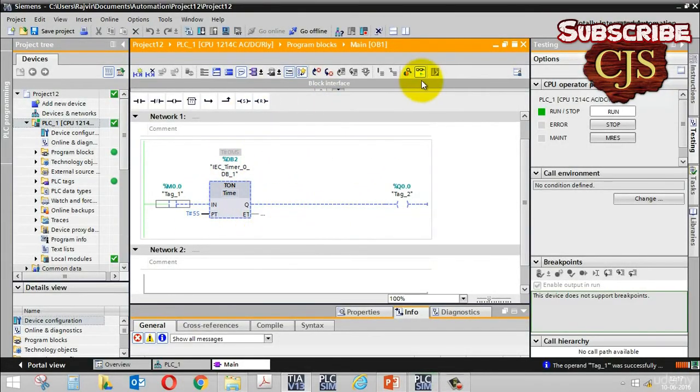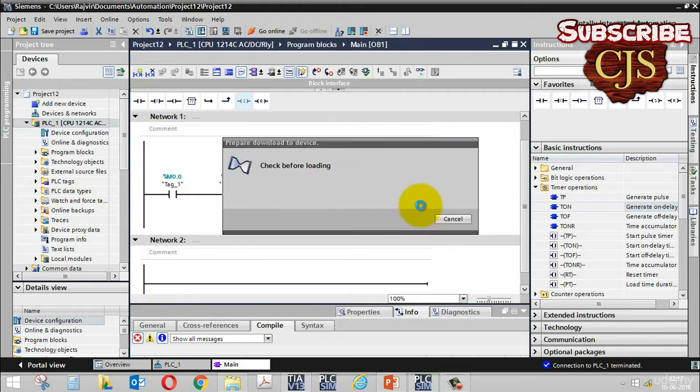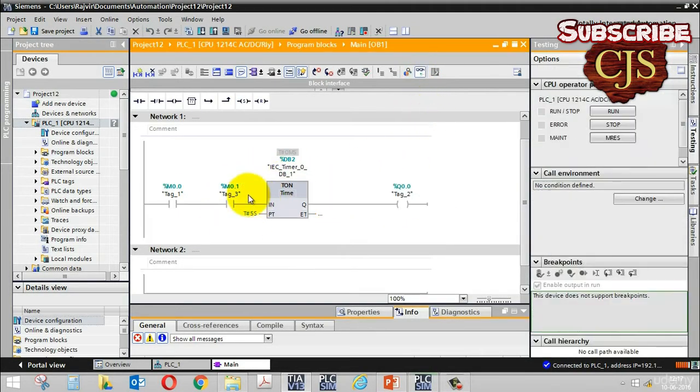Now if you want to change your logic, just turn off the monitoring. And if I want to add a series circuit here, I will write M0.1. And now you just go to download, and this will be quicker than the first initial step. So click on load, and the program is loaded. Just go to monitoring, and the program is loaded.